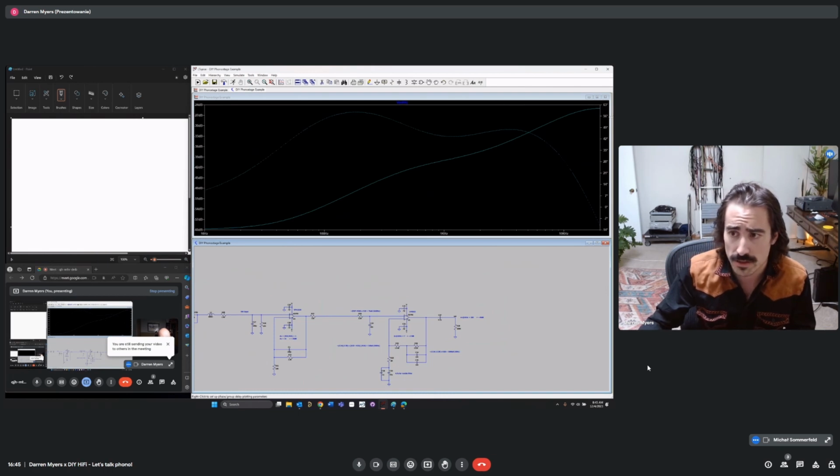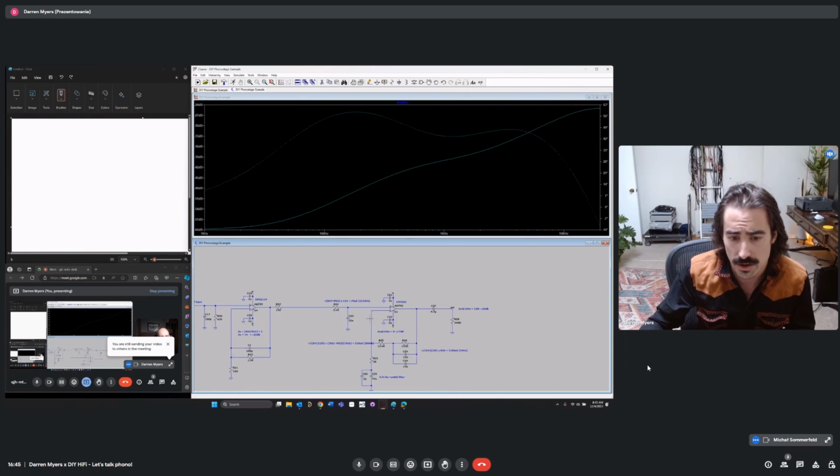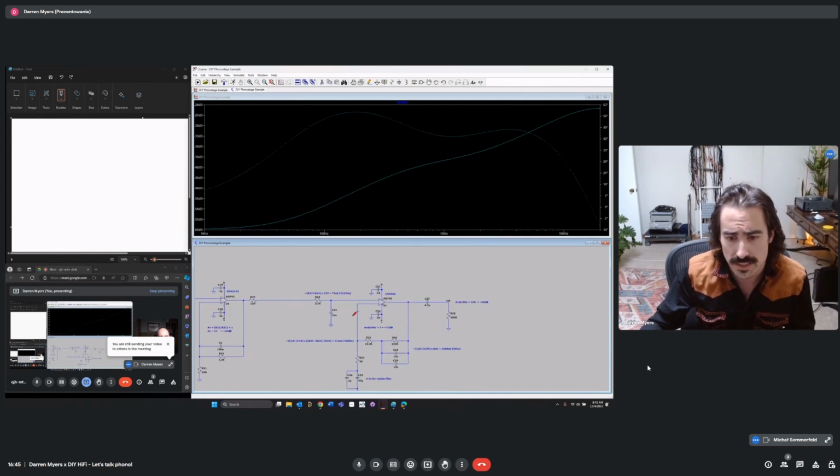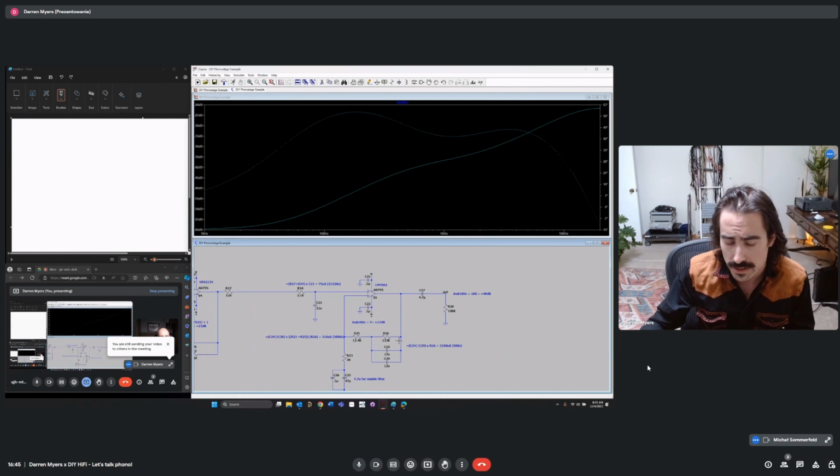So remember when we were talking about overload, and how we can clip the very top of this area easily because of how much we need to boost in the low frequency. Or I should say, because of how attenuated the low frequency is. And so what would be advantageous is to roll off the high frequency passively before we apply gain.